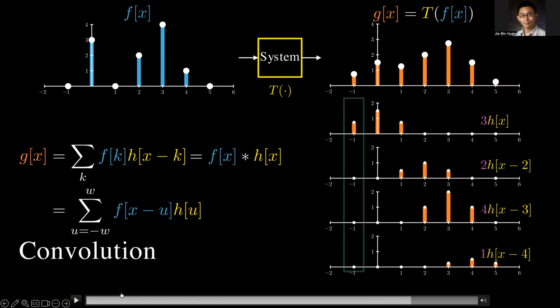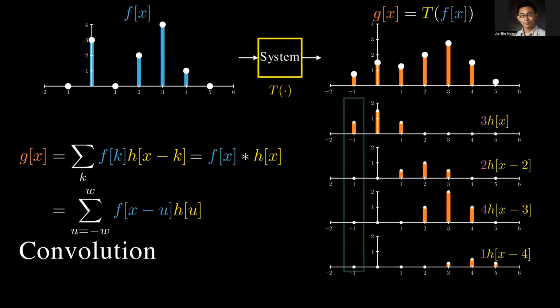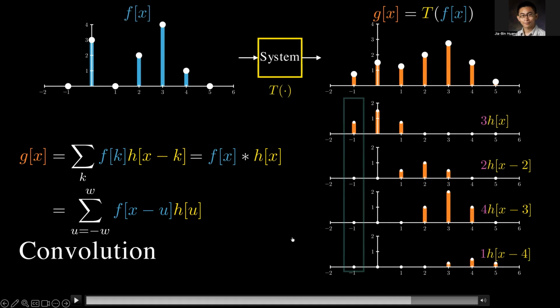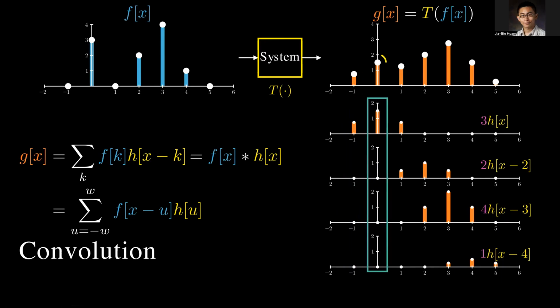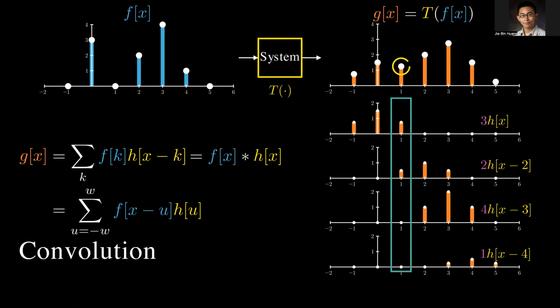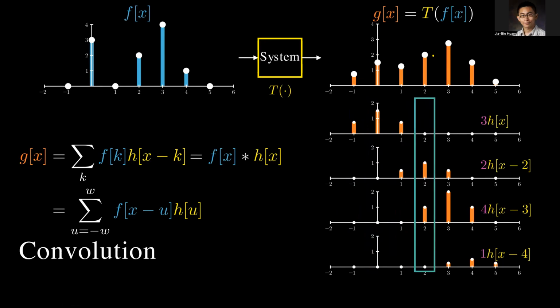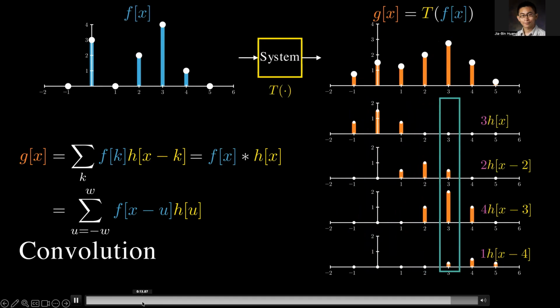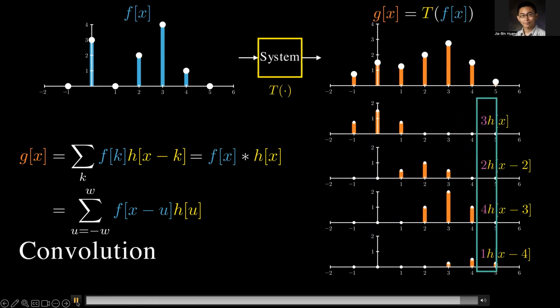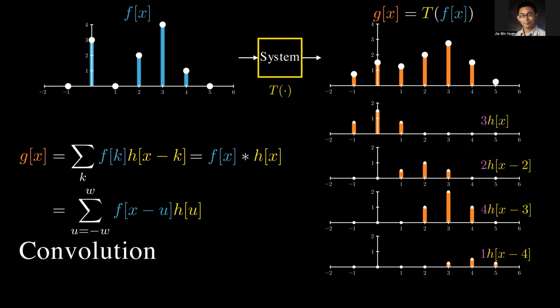So this is another way to look at this. For every location, you look at different shifted regions, and then you get a weighted average, which gives you an output signal. This is the relationship between filtering and convolution.